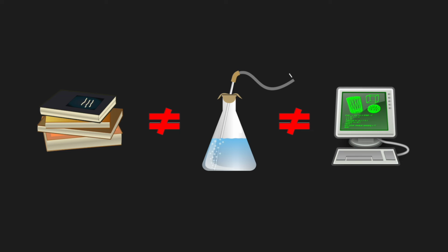In our case, experimental is different than theoretical because the uncertainty analysis that was done on the pressure gauge resulted in plus or minus 8.94 kilopascals. The theoretical values could have been slightly skewed from the pressure gauge having that uncertainty, and the computer tabulated pressure had a faulty sensor from the start, even though we found a sweet spot with it. This all in combination with theoretical differences resulted in a variety of data sets compared to each other.